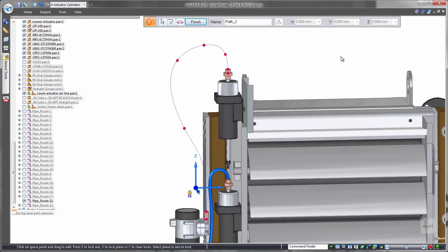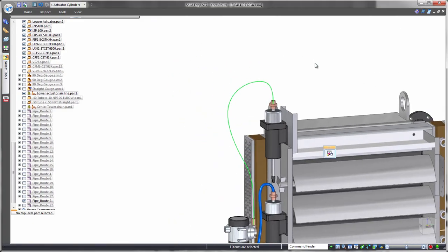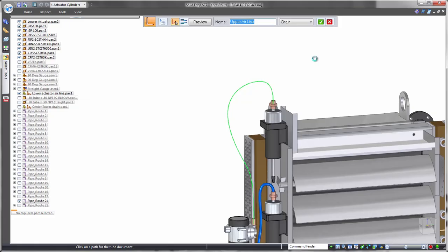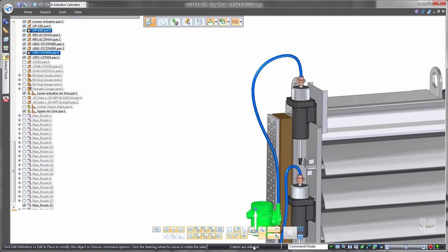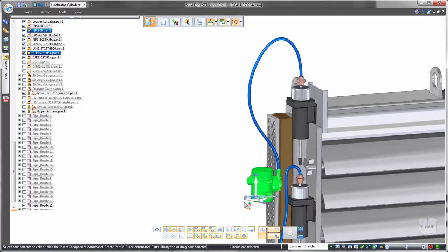To cater for this in Solid Edge, fixed length curve controls the exact physical length of the path. Watch as we move this condenser component. The flexible tube maintains its length and changes its route to suit. Valuable accuracy for validation.